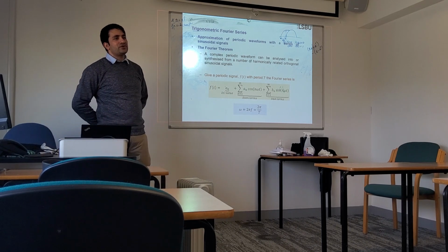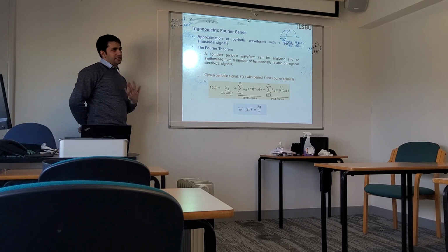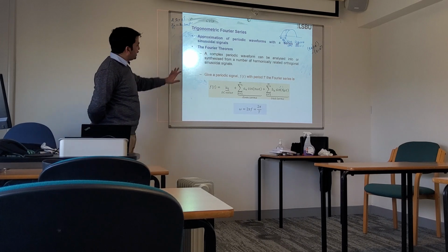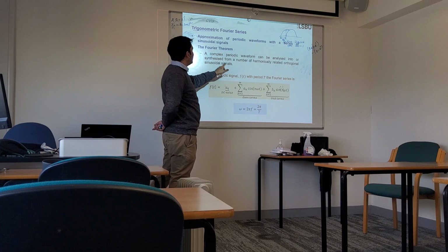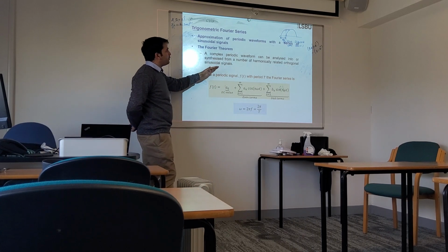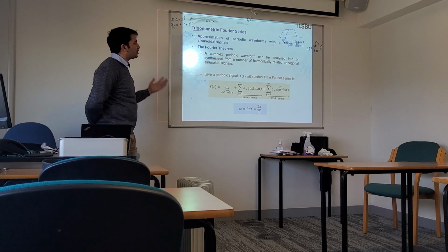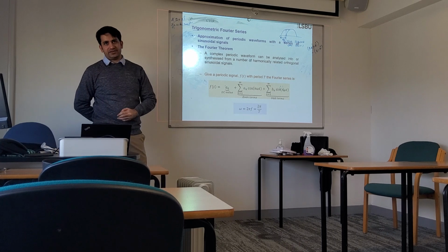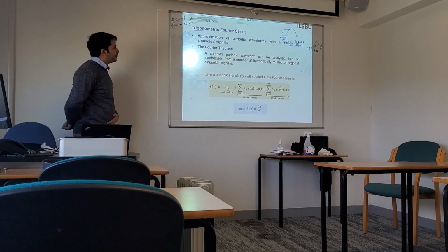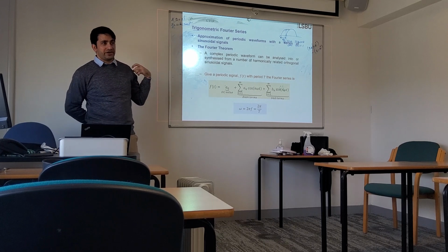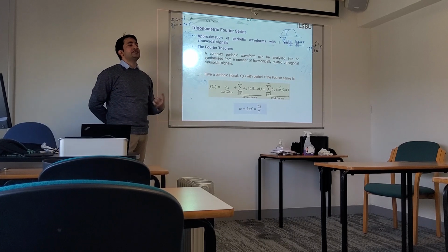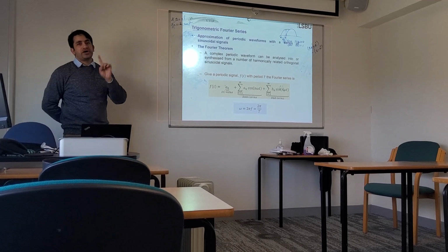Of course, in terms of calculation, it's rigorous and hard, but in understanding, you will find it easy. Here it is said that a complex periodic waveform can be analyzed into or synthesized from a number of harmonically related orthogonal sinusoidal signals. So if we have a periodic waveform, the main focus is on a periodic waveform. It means that Fourier series can only represent a periodic signal.